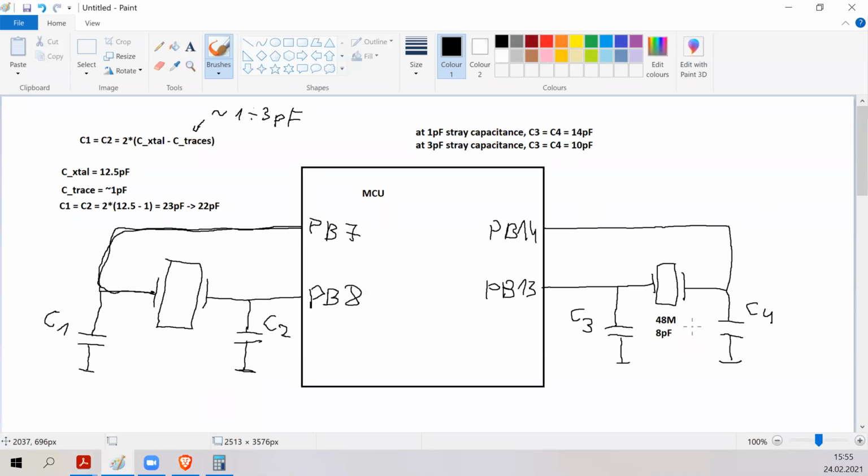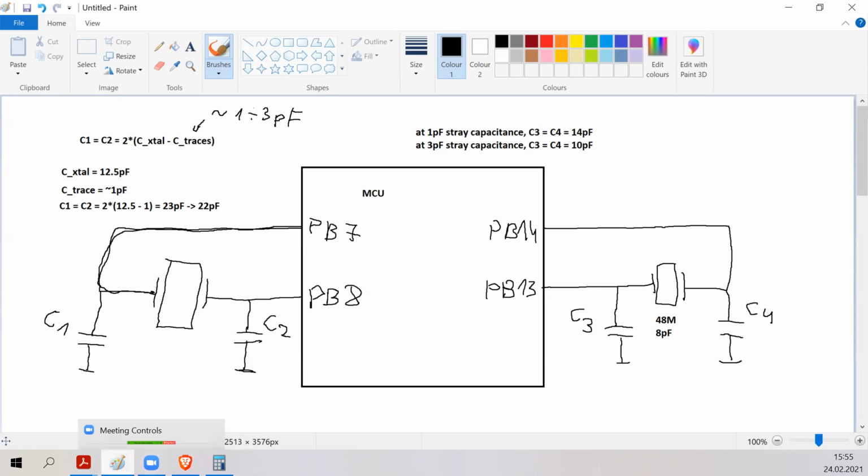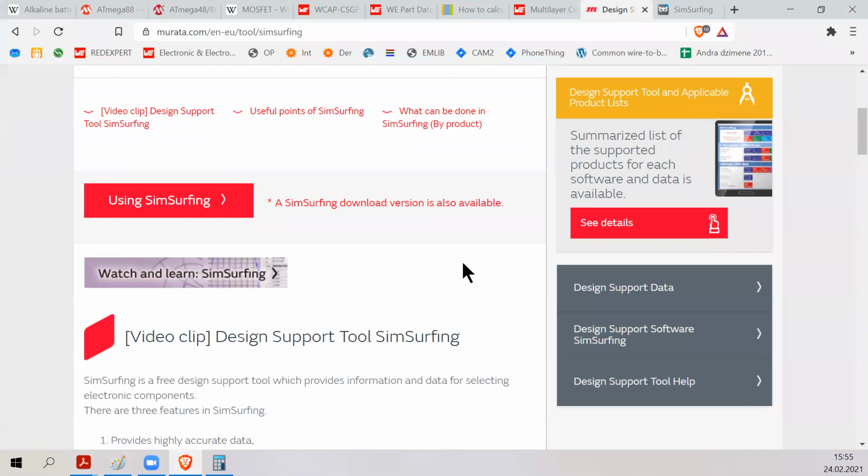So this is how you would connect an external crystal. And as I mentioned, this high frequency crystal runs in energy mode 0 and 1, and in energy mode 2, it's switched off and you have only this low frequency crystal running. So at energy mode 0, they're both running. And at energy mode 2, only the low frequency one is running, and so on. And more of this you will have an opportunity to do in the labs, which you will have in a couple of weeks.